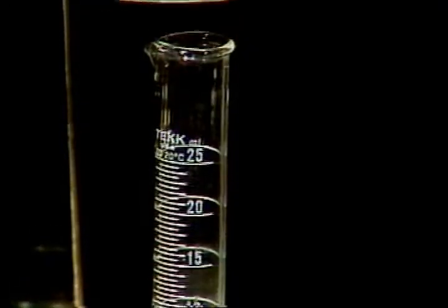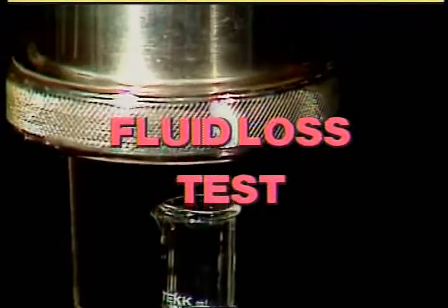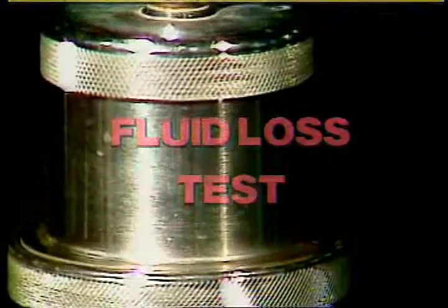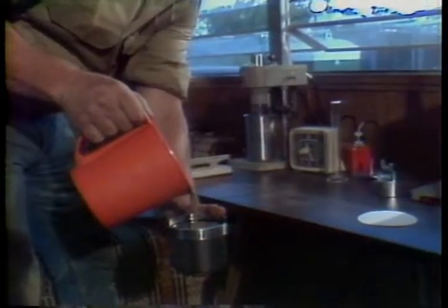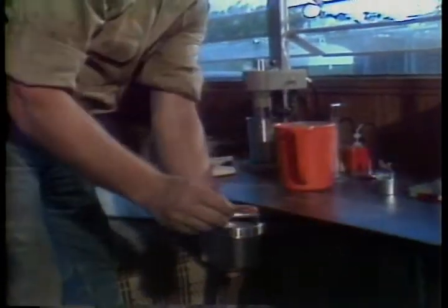The next test he'll probably do is called the fluid loss test. It's a test that'll give him an idea as to how much fluid is lost before a permeable formation is sealed and how much of a filter cake builds up. The idea is that a sample of mud is put in a pressurized container that has a 9-centimeter filter in it.